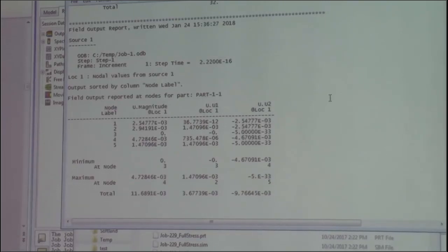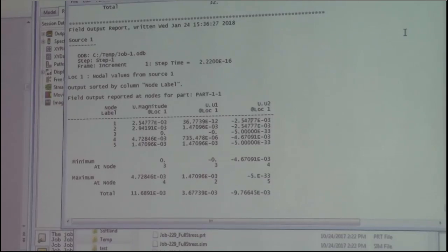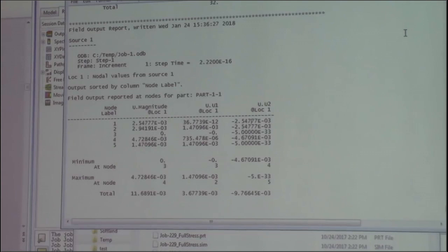What is the integration point? Probably later in your class this semester, Dr. Senka will teach you the meaning of integration point. For the truss problem, I have one point, and I use this point to calculate the stress sigma xx. For a 2D element, I don't calculate stress everywhere. I choose 4 points, calculate the stress result at those 4 points, and for the area in between, I use interpolation. So that is what the integration point means.